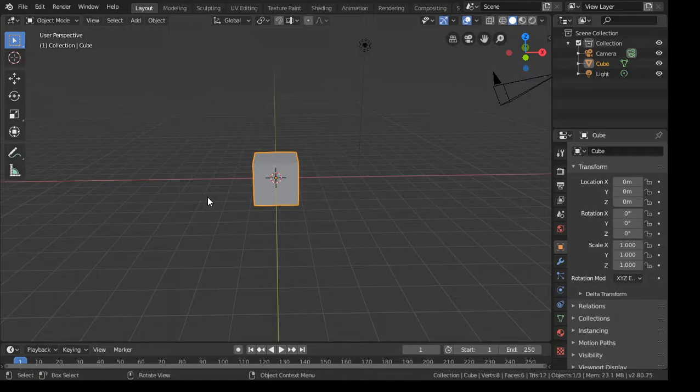Making sure Cycles Render Engine is turned on, because we're going to switch out of Eevee into Cycles Render, because Eevee was created after the TMTK was dispensed to the public, so we want to work in cycles to streamline our modeling aspect. We want to make sure UV layout is turned on, and all of these, because that will also streamline your workflow. FBX format is the format we'll be exporting into, so we want that to be checked.